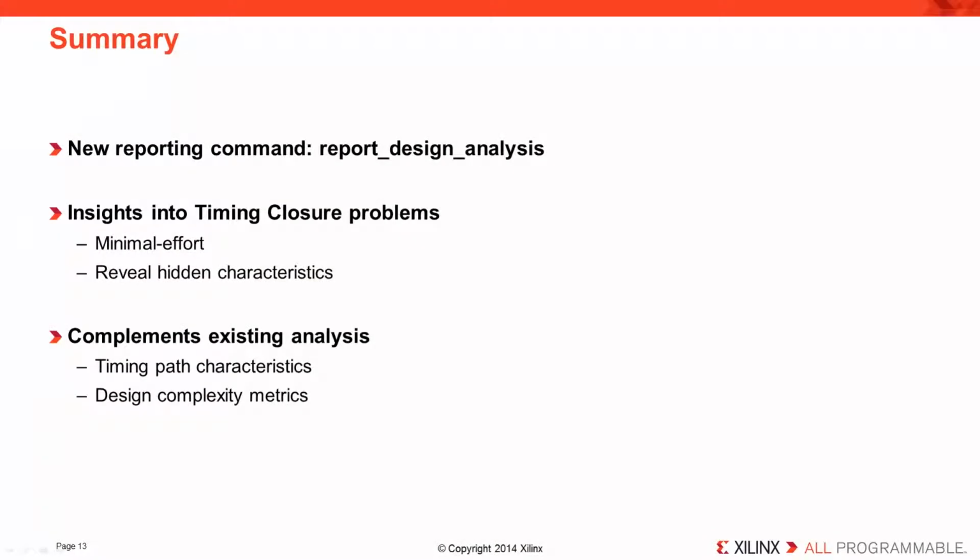So, to summarize, Report Design Analysis is a new Vivado reporting command that provides unique insight into timing closure problems. It often reveals some hidden characteristics of the critical paths and the design that are responsible for timing closure problems. Use the command to complement existing analysis with its advanced analysis of timing paths and design complexity.